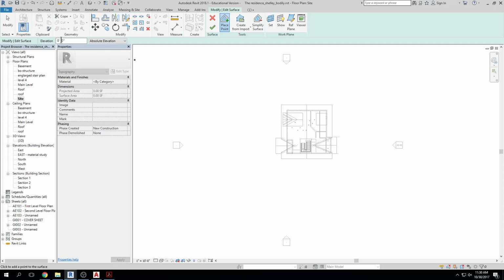I'm going to change the elevation. Well, let me do this. Let me place a couple of markers. Click, click. I'm going to place one here, one there, and I'm starting to generate my surface, moving in this direction. These are essentially 0, so from this point to this point, there's no slope. But let's make a significant upward slope. It's going to start at 0 here, and slope up, up, up, all the way to this side. And maybe we want to make it slope up 10 feet, okay?